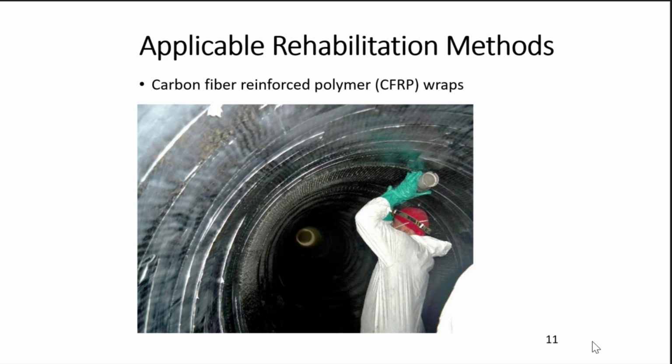So just wrapping those with a series of layers of resin and carbon fiber that when it hardens, it's quite strong. We know carbon fiber is relatively strong for its weight. And so it provides quite a bit of additional structural carrying capacity. And so, as always happens, eventually it made its way to inside of pipes. Of course, you see this is a relatively large pipe. You couldn't use this in just any old small pipe because you do need person access and needs to be